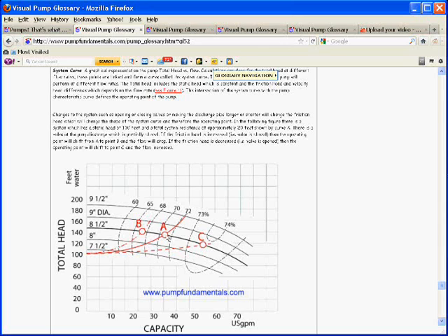Right, so this is something that's around like 35 gallons a minute and close to 140 feet of head. So we're saying that we think the pump is going to operate at this point, or maybe it's a measurement we got from the field or whatever. But anyways, this is our first point on the curve.